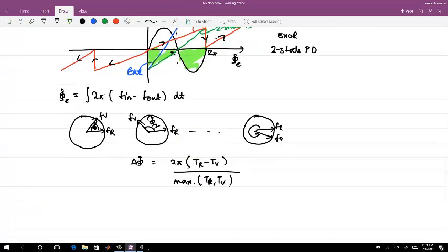The delta phi per cycle is this. Okay, and in the phasor I am showing that phi v is moving with respect to phi r. Accumulating phi 1 means at the end it is phi 2, and this is all the linear increment in each reference cycle. Okay. So does that make sense for frequency error detection?